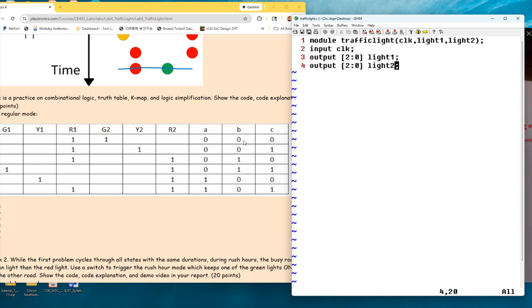Okay, so it's an internal counter. So that should be what? A register type. Okay, it's a lowercase o, right? You can start a new line and start typing. And how many bits? Three bits, right? Let's just call it in. Okay, let's call it input.